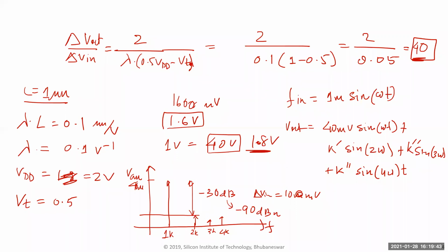And when we cover feedback towards the end of these analog lectures, you'll see that you don't have to deliberately make that small. The feedback actually automatically does that. So you can take a nonlinear amp, put it in feedback, and it automatically linearizes it, right? Like a simple op amp. If you just put it in feedback like this, what is your assumption? That these two voltages are always the same, which means the delta V in is 0. If the delta V in is 0, delta V in square is equal to 0. Obviously it's not exactly 0, but it's very, very tiny, and this tiny amount is because of the feedback.